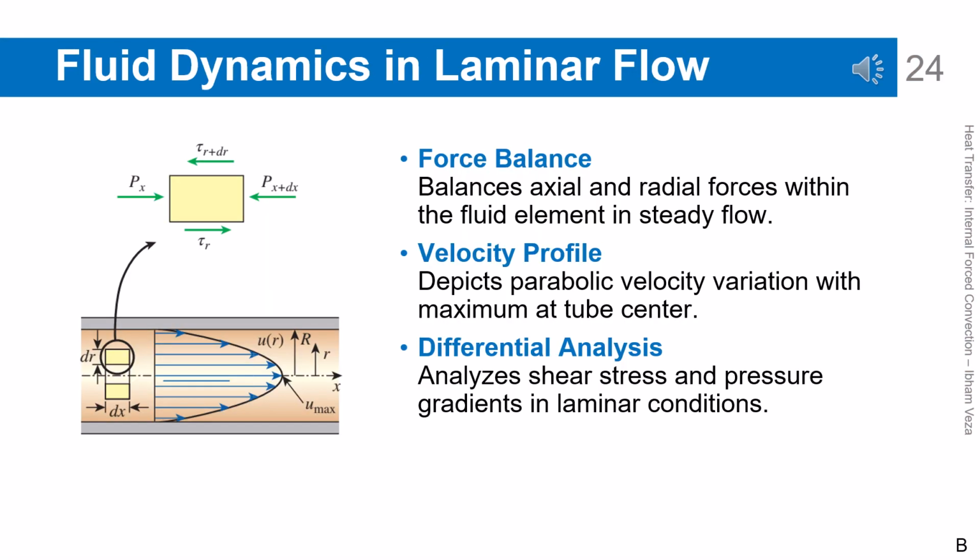Fluid dynamics in laminar flow. Laminar flow in a pipe can be analyzed using a force balance on a fluid element. Pressure forces and shear forces balance each other under steady conditions. From this analysis, a parabolic velocity profile is obtained.